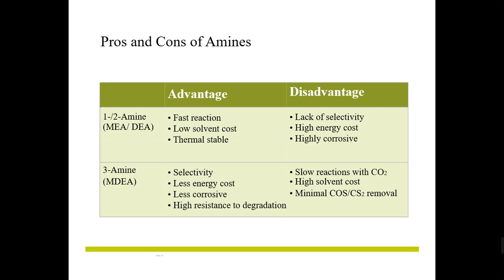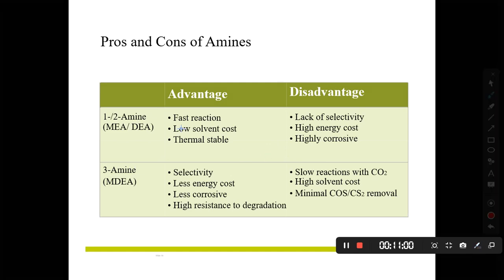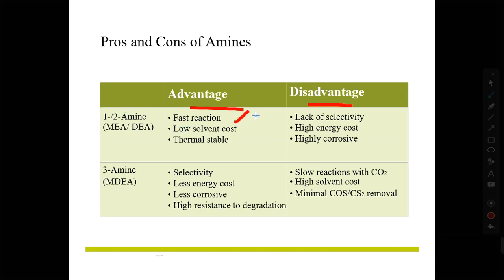So now, which one to use? Monoethanolamine, diethanolamine, and methyl diethanolamine each have their own advantages and disadvantages. They have fast reaction, low solvent cost because you need less amount of them, and they are stable also. Less energy cost, less corrosive and highly resistant.